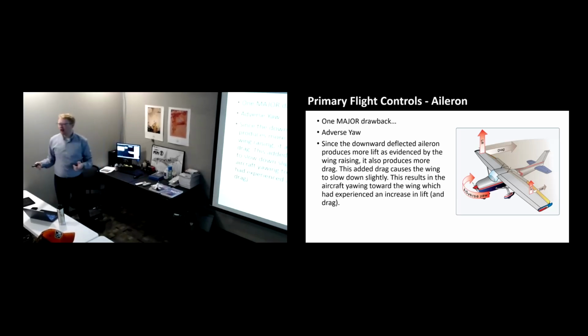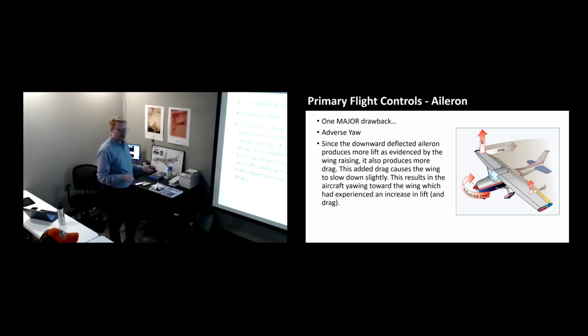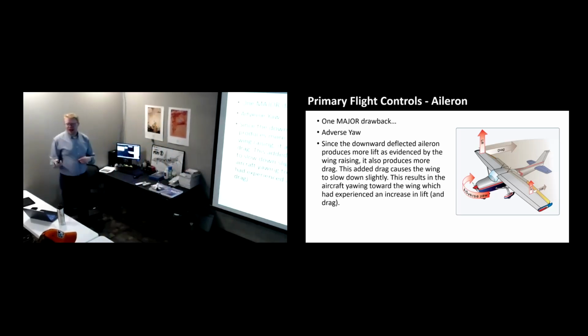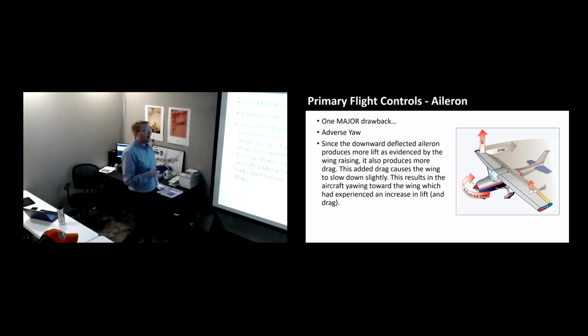Now there's different types of drag. We talked about induced and parasite drag, but remember, we're looking at what type of lift here? We're looking at, what type of drag if we're talking about lift, induced or parasite? Induced, because parasite drag is the airplane, the cables, aileron cables. Those are causing drag. The antennas, those things. And that's what's causing parasite drag. Induced drag is our byproduct of lift. So induced drag is directly correlated to lift. So if we're producing more lift, we're producing more drag.